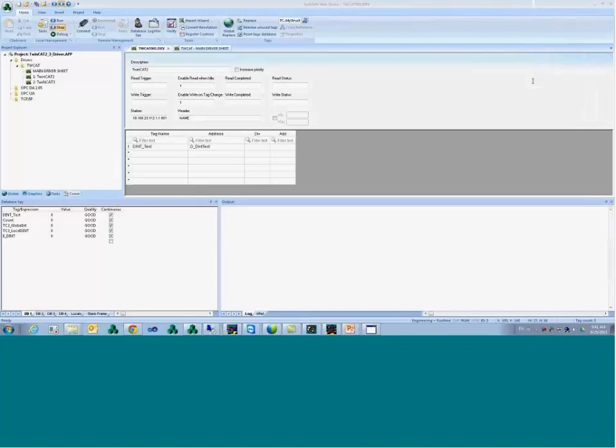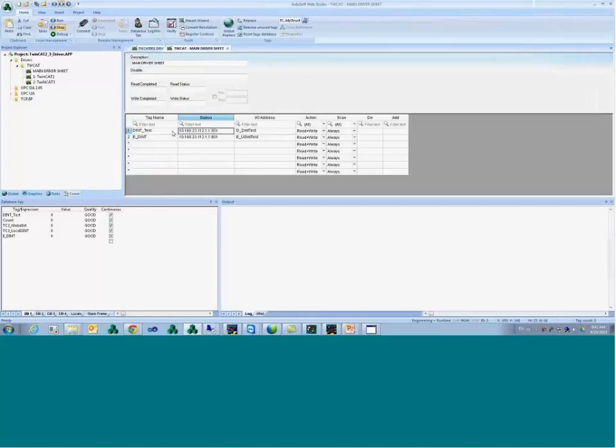And that would mean probably creating the driver sheets on the fly or something like this. Well, you can have tags. For instance, on the station fields, it doesn't have to be hard-coded, so I could put a tag in here between curly brackets and then change the value of this tag whenever I want. So that could be on the boot up, so you don't have to have a hard-coded value there. But recreating the driver sheet, that's a little bit more advanced.